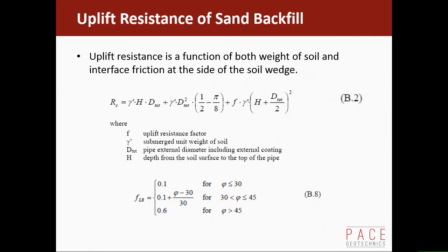was this equation, which completely threw me, and I apologise for that. I had literally copied it out of DNV, and it was the first time I'd changed it, and I thought it's the same equation, but that number in the original one was not the current version of DNV. So I thought I'll change it, and I missed that term is not in the equation in the current version of DNV, and it should be there. And if you look at DNV, you'll see it gives you the further up equation B1 actually breaks out F into K naught, tan phi, with submerged unit weight. Which is what I was explaining yesterday. For your purposes, just taking F as the uplift resistance factor is fine, and I use that. So, sorry about that, guys.